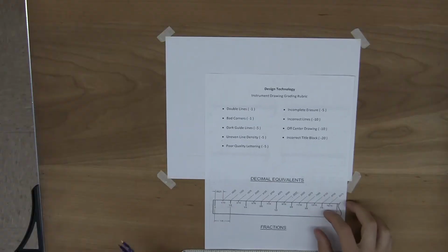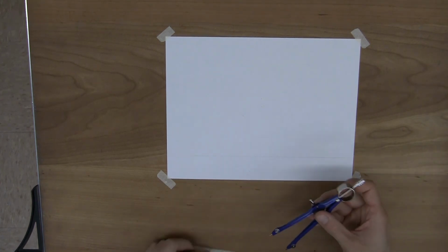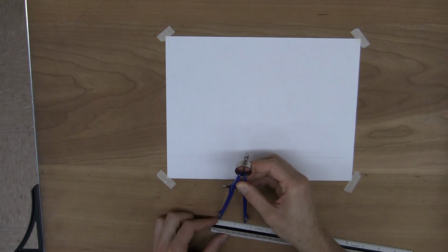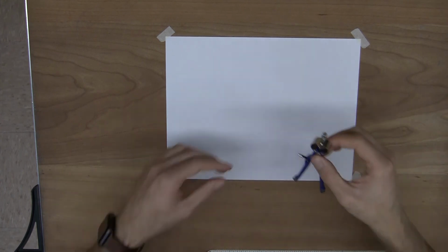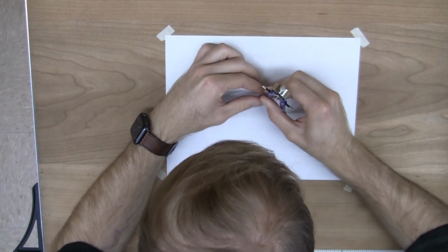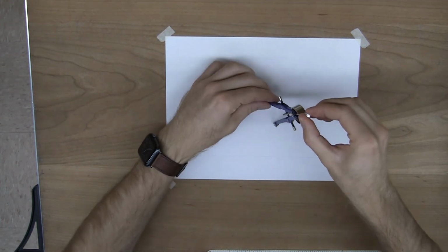So there's 2 arcs on there, 1.62 and 2.56. I'll start with the smaller one. What's 0.62? Well, 0.625, 5/8 of an inch. So 1 5/8. Remember, I'm going to poke right through the paper, right into the board. And looking at the drawing, I don't need to make a full circle.